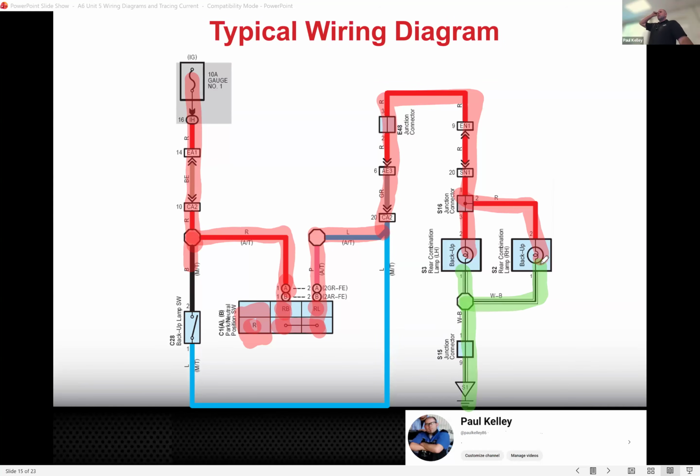And then the method, which we're going to mostly focus on tracing now, but the method would be the same. If you trace it and then you go to poke and do diagrams and back probing and whatever, all you really got to do is look at the color. If the color's red, it should be source voltage. If the color's green, it should be ground. And if you get a 0 voltage reading on something that's highlighted red, something's wrong. Kind of makes sense? Like power's not making it to that point.